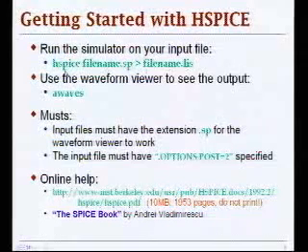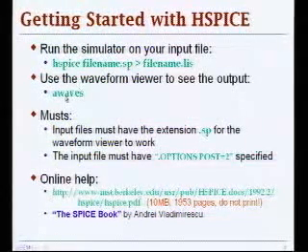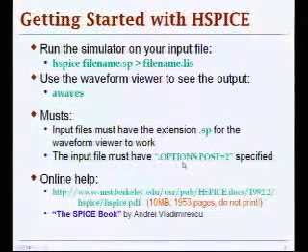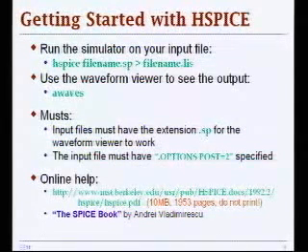And in order to view the results of your SPICE simulation, you need to run this waveform viewer that is available through the command awaves. And as I mentioned, input files must have an extension sp, and the input file must also have the option post equal to specified. What it does is essentially enable you to save your simulation results and see them later on in the waveform viewer.